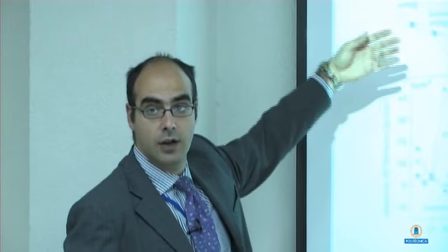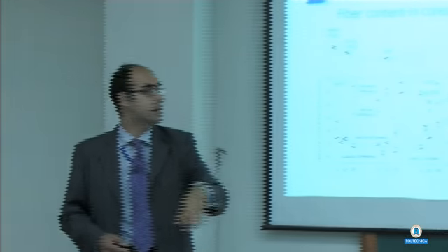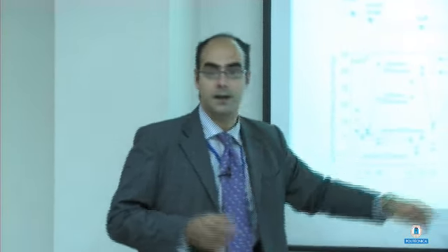And also we checked the dispersion of the fibers in different positions along the axis of the element. Here they are just labeled with numbers, but these were about at half of the span, these at 1/4, and these at 3/4. And you can see with the vibrated concrete, the scatter of the content of the fibers, the cores were crushed afterwards and the fibers were separated with a magnet, while you can see here the much reduced scatter when you have self-consolidating fiber reinforced concrete.